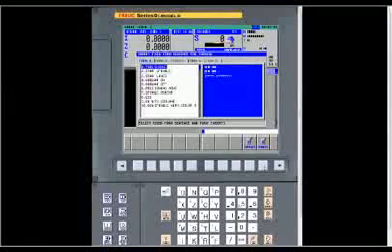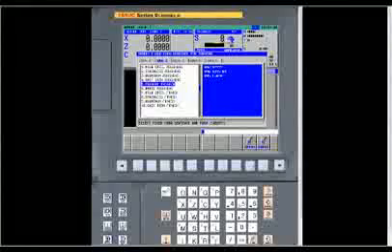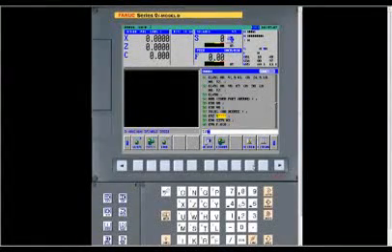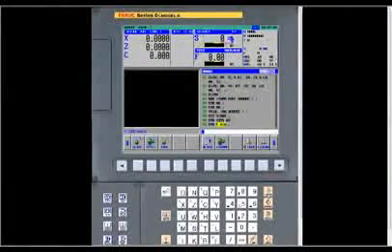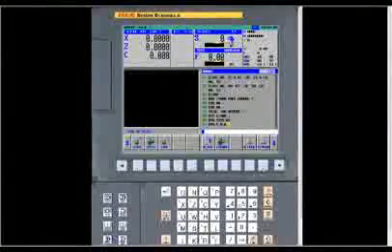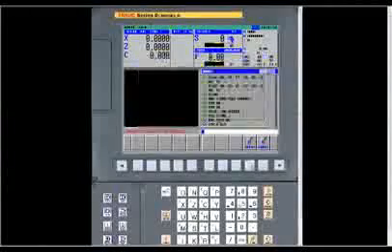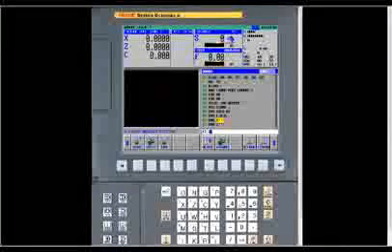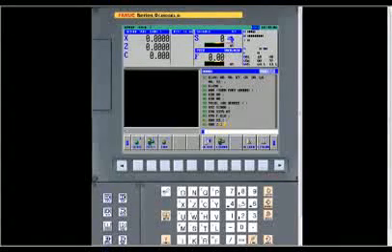Then we go to fixed form. We want to do our cut speed, our preheat tree cut speed. And again, we limit it. That's 1500. Alter that. And we want to do a position move, just like I told you. What I always like to do is a positioning move to know where I'm going. We insert that. Again, X 3.1, but we're still using the same material. Alter that. And Z at 0.1, alter that.